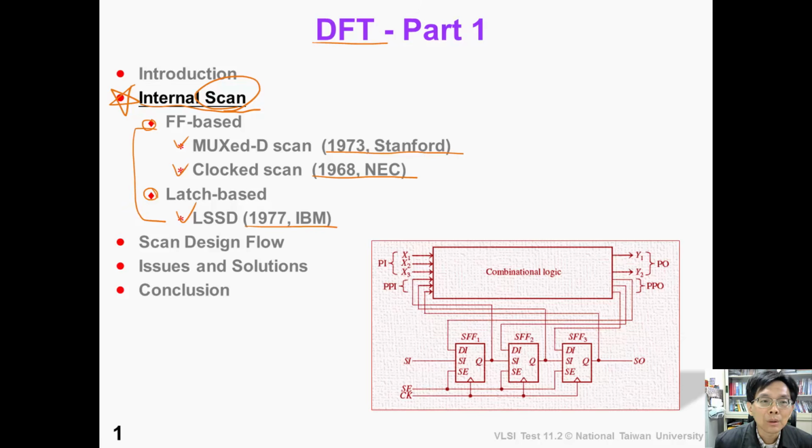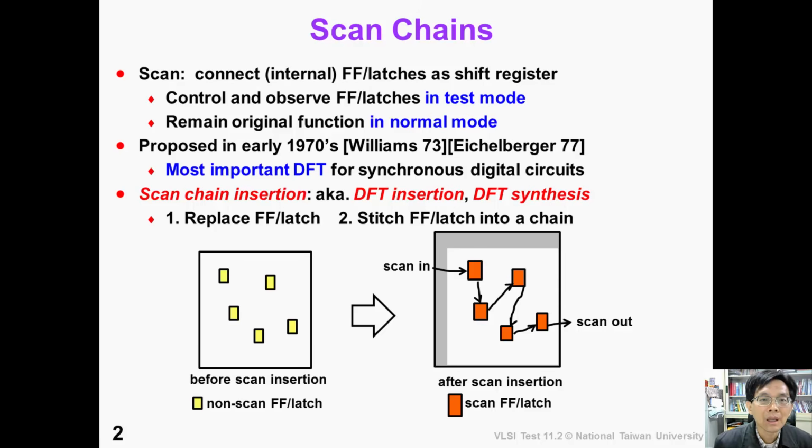In this video, we will first talk about the general concept of scan. The idea of scan is to connect internal flip-flops or latches as a shift register so that we can control and observe the internal flip-flops or latches in test mode.